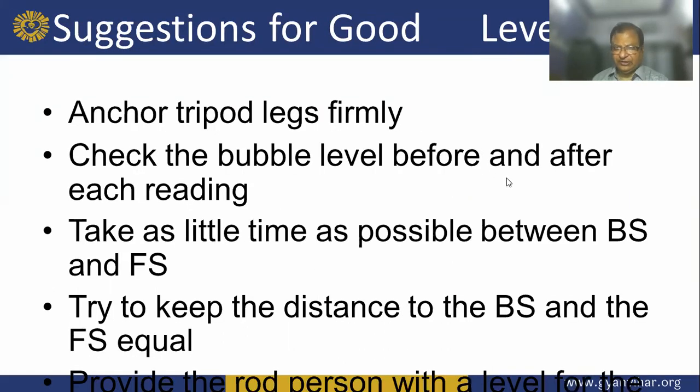Suggestions for good leveling. Anchor the tripod legs firmly. Check the bubble level before and after each reading. Take as little time as possible between backsight and foresight.